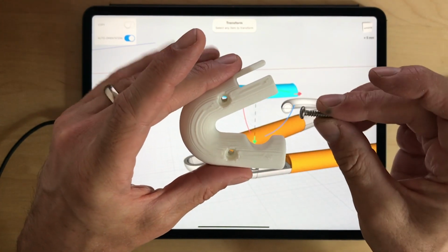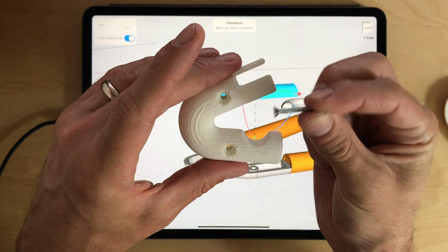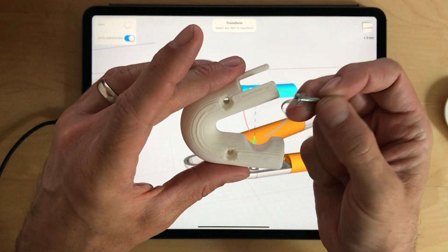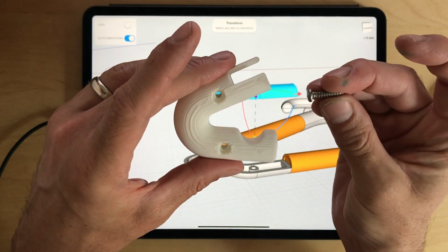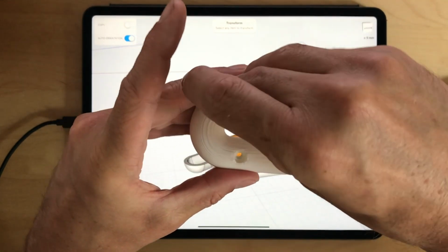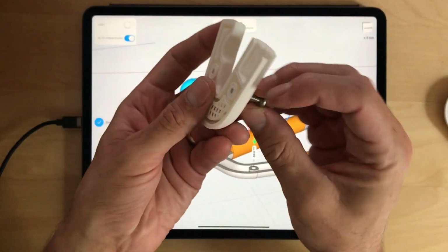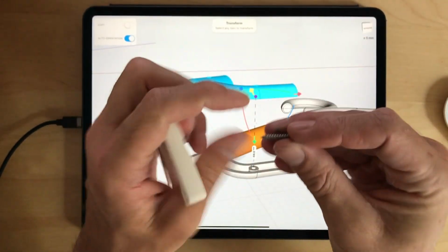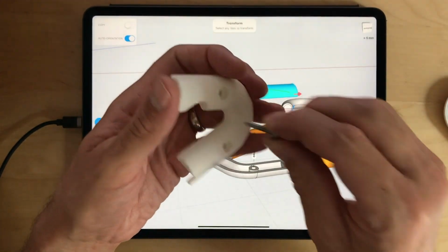I was just looking when I made this prototype what type of screws I have. This was nice, but unfortunately this screw was too long. It would stick through. This one has a wider head, but it wasn't as long, so I could screw this in there. With a caliper, I measured the diameter of the threading, and then I made the plastic a little bit smaller.